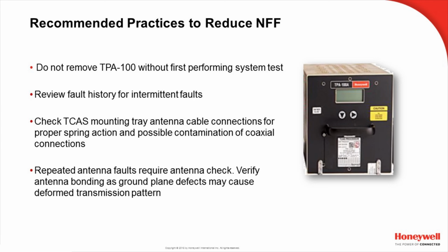And the last thing here, repeated antenna faults are going to require an antenna check. And as I mentioned before, you need to verify antenna bonding has been properly achieved, that you have a good ground plane, because this will affect the TCAS transmission pattern, the surveillance volume pattern, and will also likely result in TCAS antenna